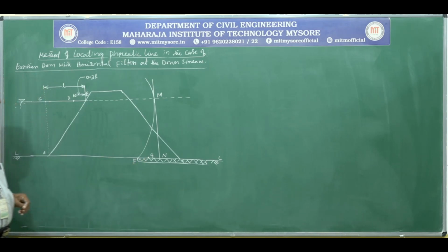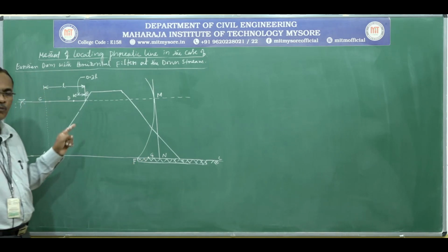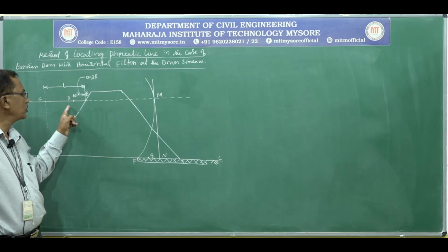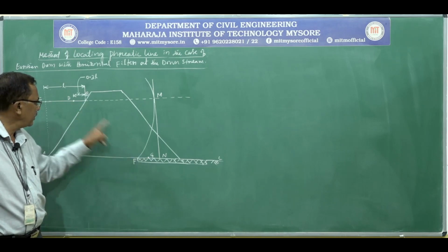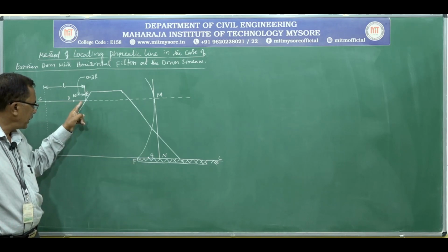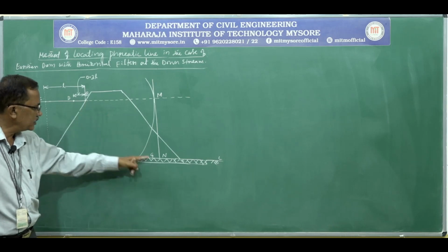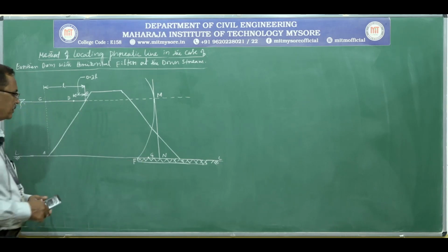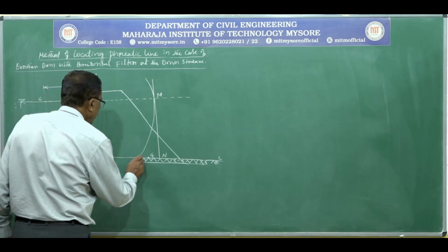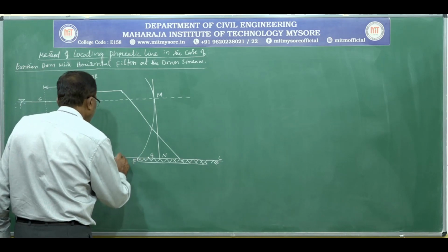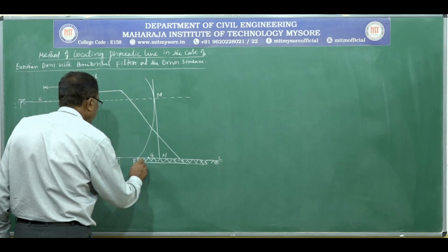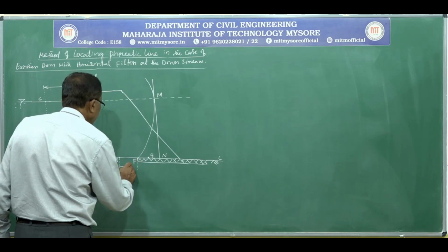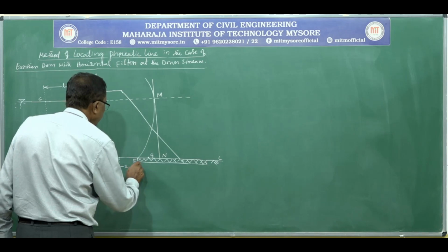Next, in order to obtain the smooth curve of this phreatic line, we can locate the intermediate points between the actual commencing point of the phreatic line B and G. For that, select any distance or any point, say P1 at a distance x1 from F.